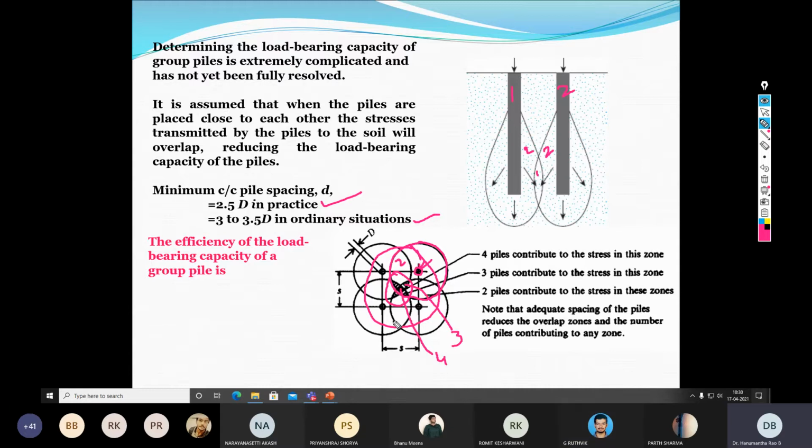Sir, here the soil is settling, but not the foundation, sir. Why will the problem arise? See, once the soil is settling, it means there is a separation of the particles. Suppose the settlement exceeds 10 millimeters, how does the soil accommodate it? To accommodate that settlement, a gap has to form within the soil sample. When it is settling, obviously a gap will form. Once a gap is formed, that has a negative impact on the overall foundation system.